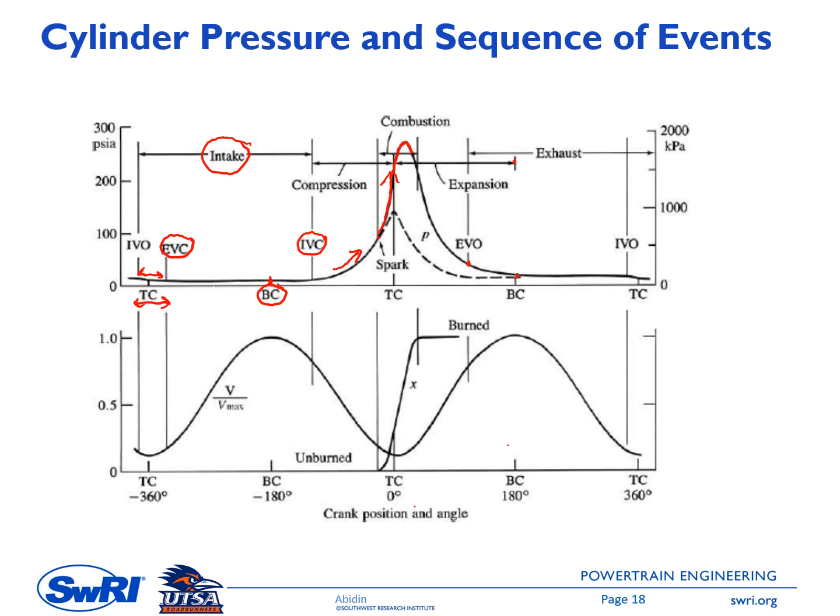And then the second part of the exhaust process is between BDC and TDC, where the exhaust gas will exit the chamber because of the piston displacement. So we have the exhaust process from the exhaust valve opening until this point.